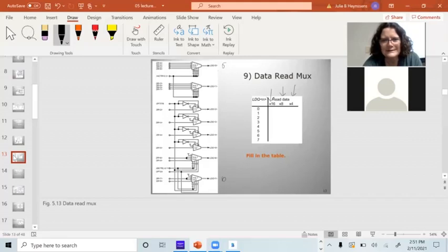Now, if I'm sending out 16 outputs, I'm going to want this signal right here, LV0, going to my 0, 1, 2, ... 7, going all the way down. If I'm only reading 8 outputs, I'm only going to use half of this. So the way I'm going to read 8 out is I'm going to read half the 16-bit data on one cycle and read the other half on the other cycle.